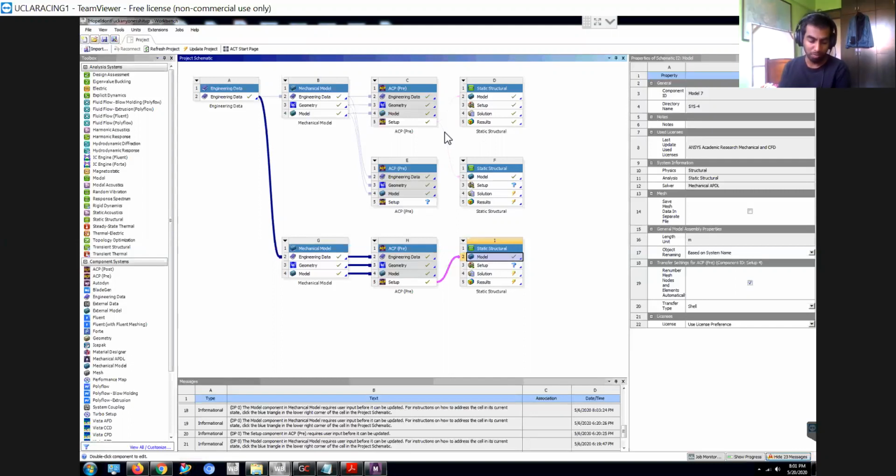This is because, think about it, if you're driving a car, you don't want your steering wheel flopping around or having some give, or your seat moving around and flexing underneath you while you drive. So you have to carefully consider the deformation. Certain things like the front wings will also have a certain amount of deformation based on rule compliance, so you'd have to look up the various rules and see what they say about how much deformation is allowable.